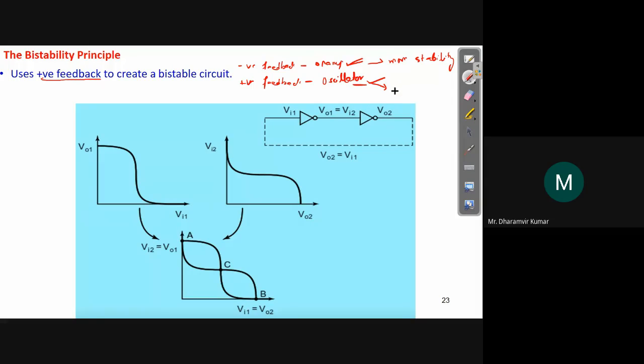But here the gain rises continuously. It goes out of bound after a certain period of time, ideally. But we limit this gain to a certain limit to make use of these positive feedback circuits. Negative feedback is very widely used, and you will see most of the time negative feedback circuits, but there are some good applications where the positive feedback concept is used.